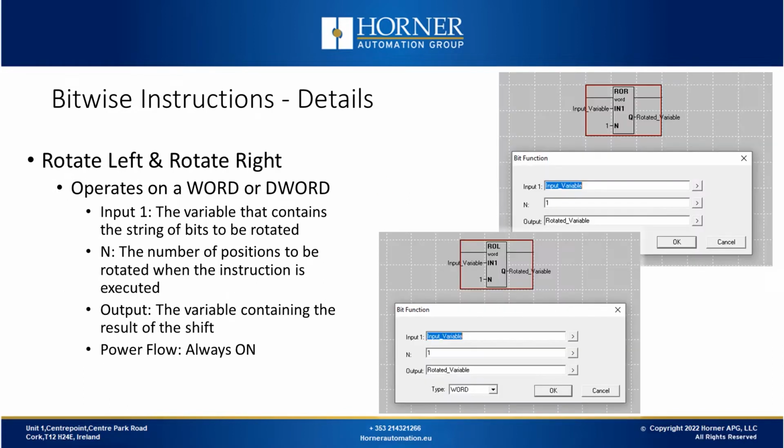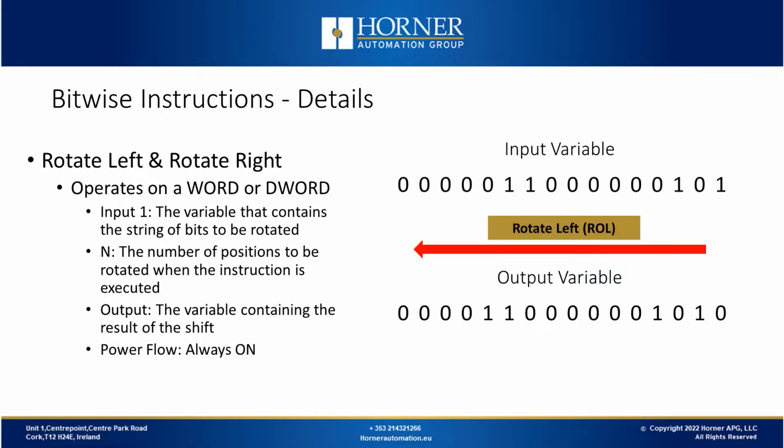We also have rotate instructions where we can rotate left or right. These are similar to the shift instructions. The only difference is that you don't have a 0 that you're shifting in, and you don't have a bit that you're shifting out. It's completely self-contained. Let's look at the bit pattern.